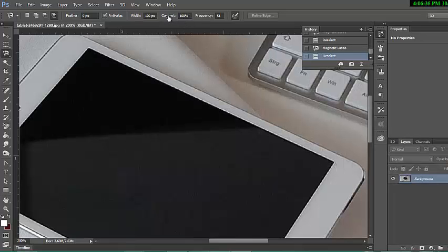The next option is contrast. It means how much contrast it is looking for. If we have 100% contrast, it clearly looks for a line which is very contrasty indeed. Whereas if you have 1% contrast, then it will find lots of things that are not contrasty.